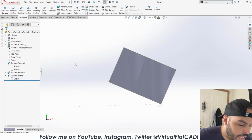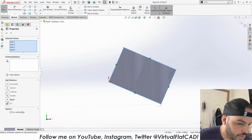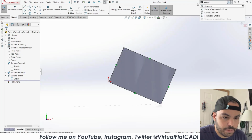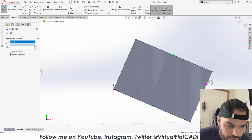So let's show my sketch here. Let's grab a new sketch on the front plane again. I want to convert these, but let me turn that into construction. And to have equally spaced divisions, I'm going to use the segment command. Segment. So I can say, let's break that up into segments. I think 4 is pretty good.